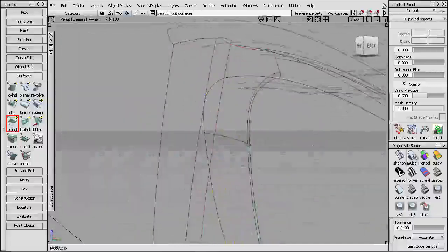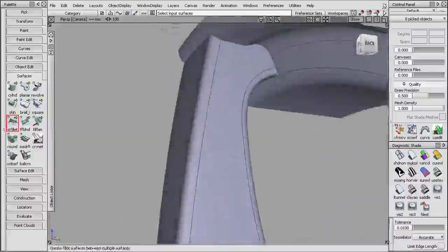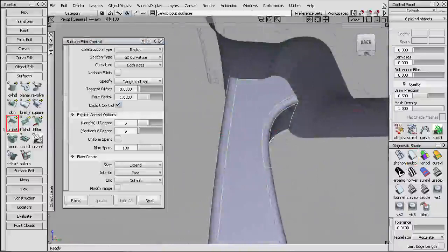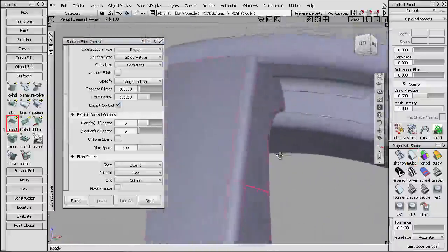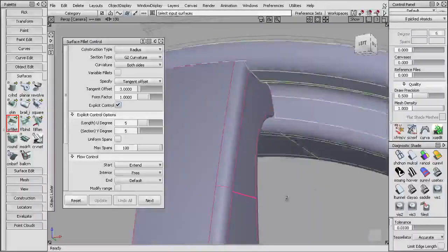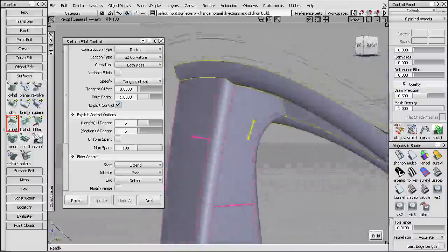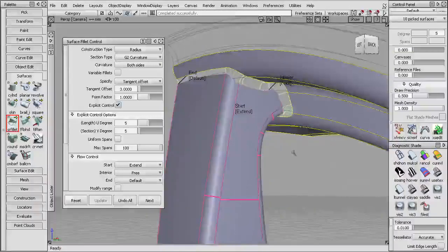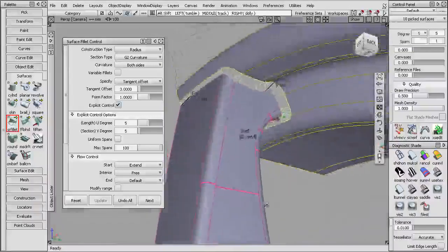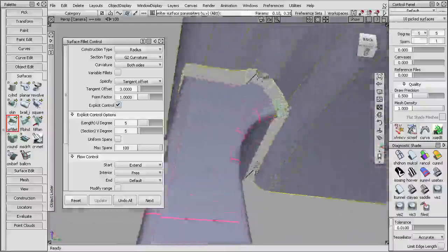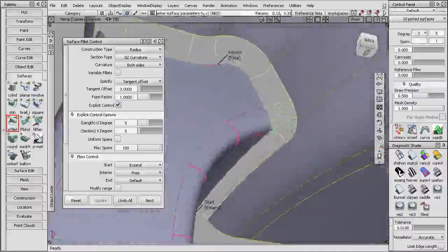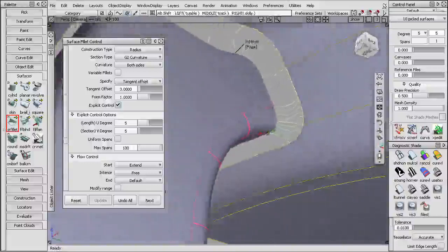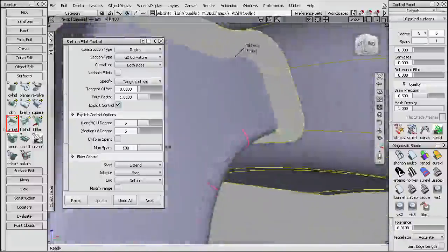So now, around the spoke, I've got a ribbon of tangent continuous surfaces, which means I can now fillet all of those surfaces against all of the rim surfaces. And I'll just check the arrows, and that's the right direction, and build the fillet. And it's done a good job. And it's even gone round that tricky corner at the back that crosses these 2 surfaces. And that's because the surface fillet isn't concerned with edges, it works from the body of the surfaces that it's blending between.